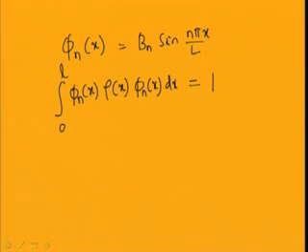So you can normalize the mode shape using this formula, similar to what you did for the multi degree of freedom system, where you took the weighted modal matrix P and found P transpose M P equal to I. In this case, you got the diagonal terms as 1.